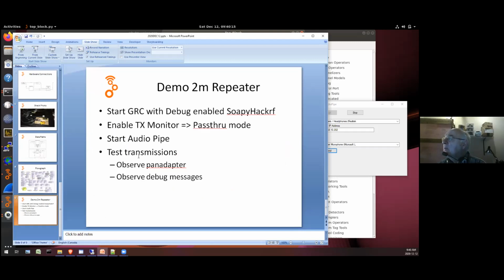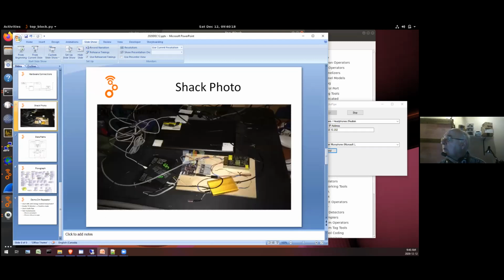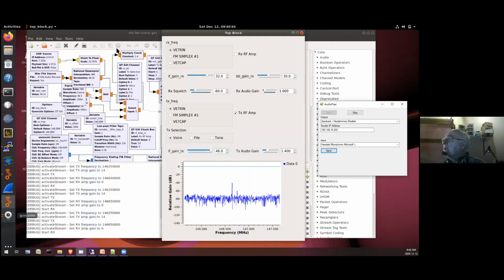There's one thing I missed, but you'll just have to take my word for it. When I started transmitting, this signal went high, went through the PIC microcontroller, and keyed the power amp and set the relay in the transmit position. And so what we should see here...